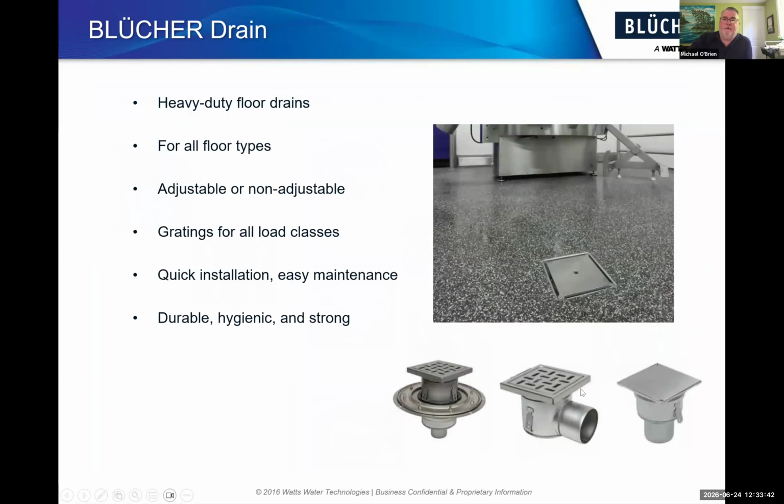We do heavy duty floor drains for industrial applications for all different types of floors, whether it's polished concrete, tile, epoxy or urethane. If it's above grade and you need a surface membrane or a subsurface membrane underneath, then this one here on the left at the bottom has a clamping ring around it so that you clamp it down onto that subsurface membrane.